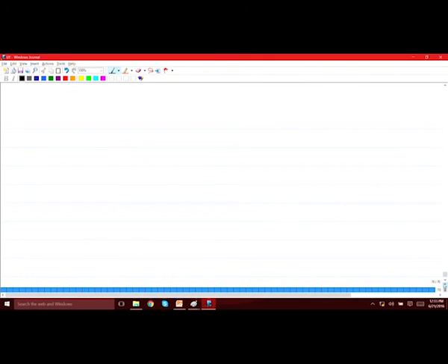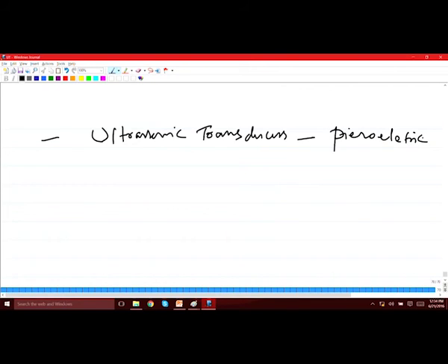And then we learned about different types of transducers and the construction of the transducers. So, we learned about two types. One was piezoelectric transducers, which are also known as electroacoustic, and then we have seen one more type which are known as EMAT or electromagnetic acoustic transducer. So, in this case we saw that you need a couplant to exclude the air gap between the probe and the sample surface, and in this case we saw that in this EMAT probes you do not really need couplant, it is a couplant free operation.